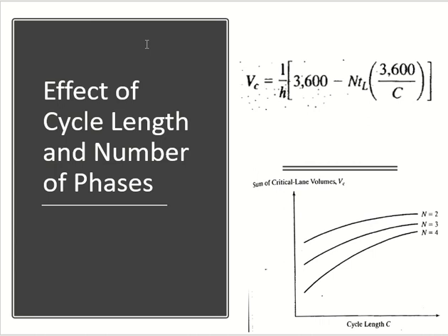Now look at the equation. In this equation, there are 2 values which depend upon the drivers or the intersection design, which I cannot change. For example, headway. How much interval the drivers keep between them is up to them. I can observe it, I can go to the field and note it down, but I cannot change it. I cannot force the drivers. When you go for your driving lessons, they tell you to keep distance, and you don't listen. The other thing is TL, lost time. Again, how much extra time the first 3-4 cars take, I cannot change. All-red time depends upon the intersection design.